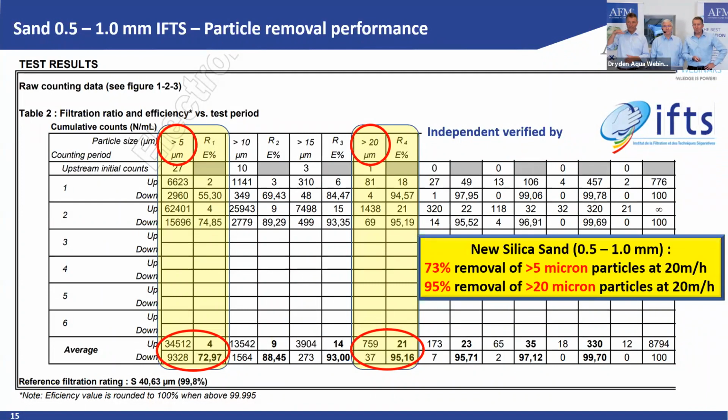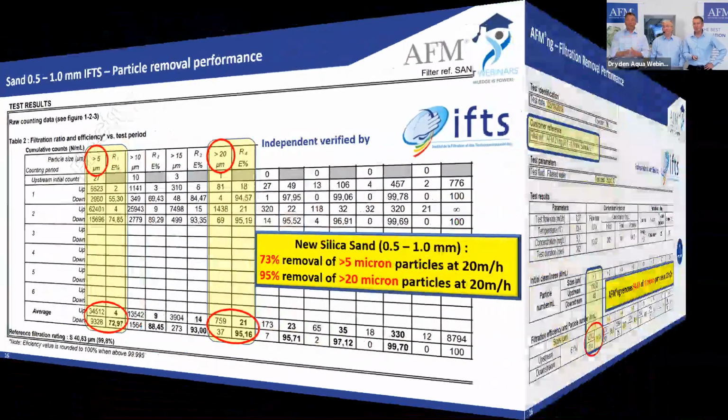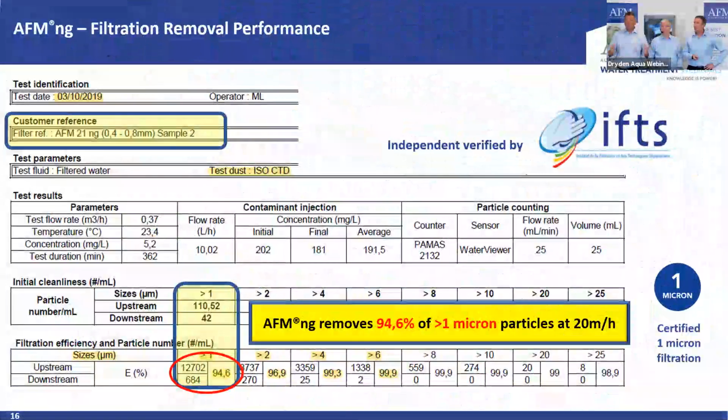We always put this line, you know, media filtration is always nominal filtration. It's not absolute filtration. Yeah, sure. And some measure it at 80. 80, I think, is completely nonsense. Others on 90. We wanted to be on the very safe side. This is why we put the threshold line. Do you call it threshold? Threshold on 95. Yeah. Or limit or whatever. Okay. So what it is, we filtered down with sand, the very best sand before biofouling to 20 micron.